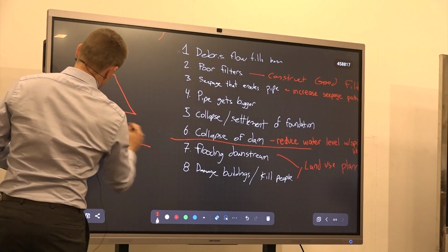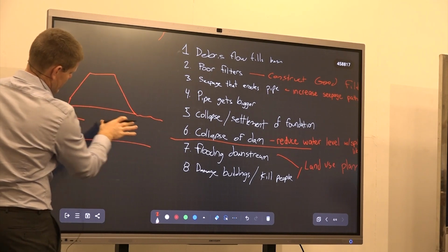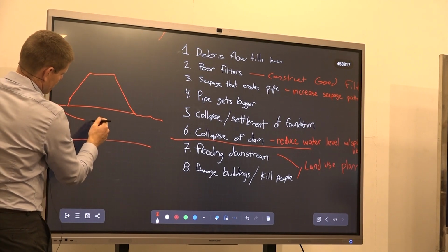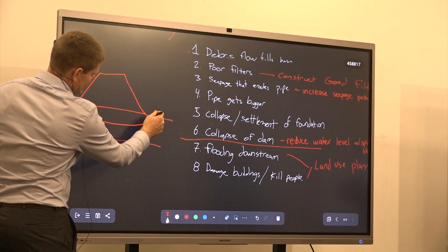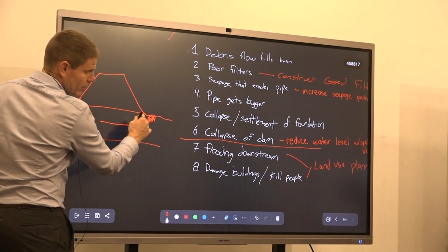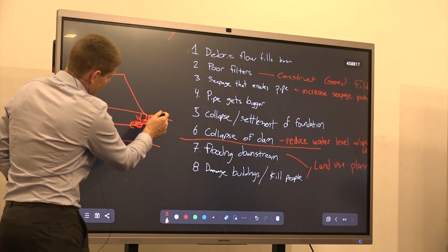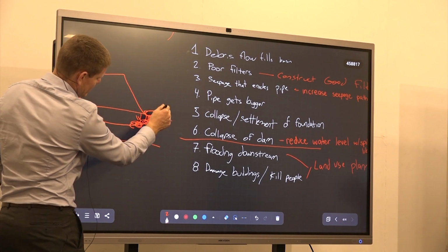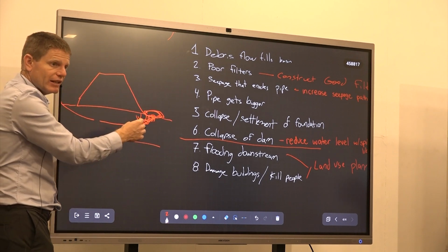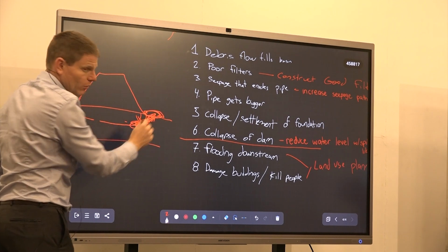So if you have a barrier, you have a structure, you have seepage underneath here, let's say there's debris there, or sorry, the foundation here. The erosion begins here and it starts to work its way backwards, right? And then you get collapse of these materials in. Well, if you have equipment here, you can start to place material here during the emergency so that you don't get as much material eroding outwards.